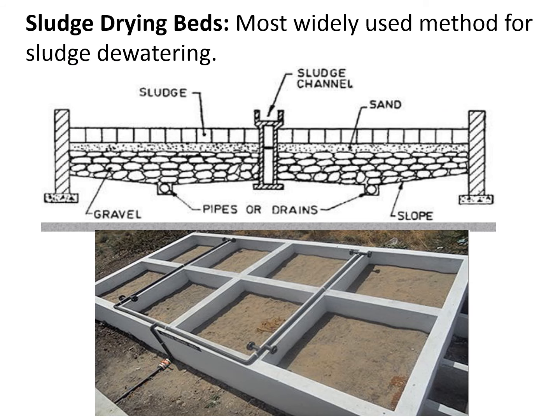And the last one, after the digested sludge, this digested sludge is to be applied for further removal of moisture, and this is generally called sludge dewatering. The most widely used method in India is the sludge drying bed. They are just simple beds consisting of sand material and gravel. You just have to apply your digested sludge over that and dry it for 14 to 15 days, and all the moisture will pass through, and the pipes and drains collect this